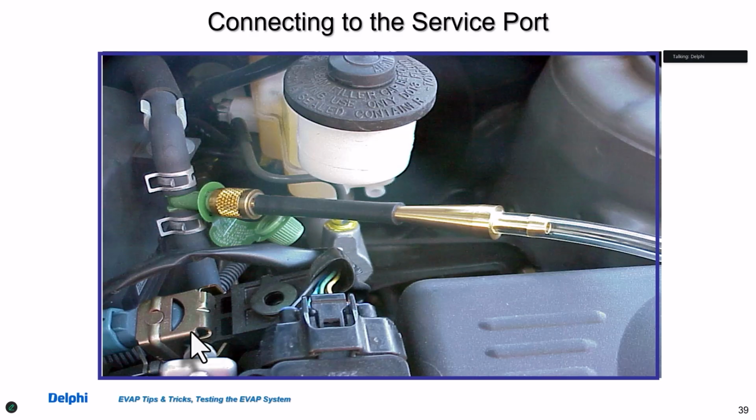But when you have it, you have these adapters. And always remember, if you go in there and you do what I'm doing here, it's recommended that you take the valve core out first before you start applying any of this system. And remember, this is important. The Schrader valve in there is a left-hand thread. So it comes out the opposite way that you would normally take it out. So when you're tightening it, you think you're tightening it, you're actually removing it. So very, very important.